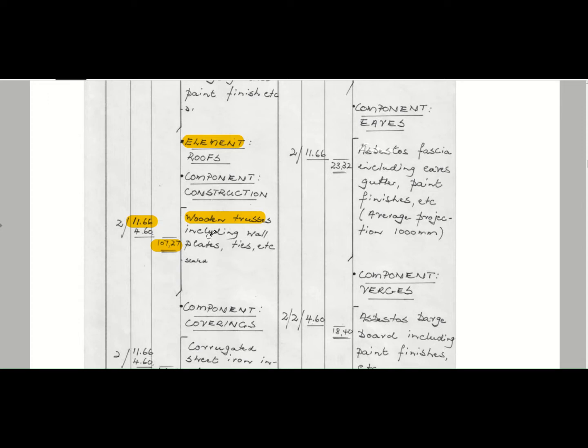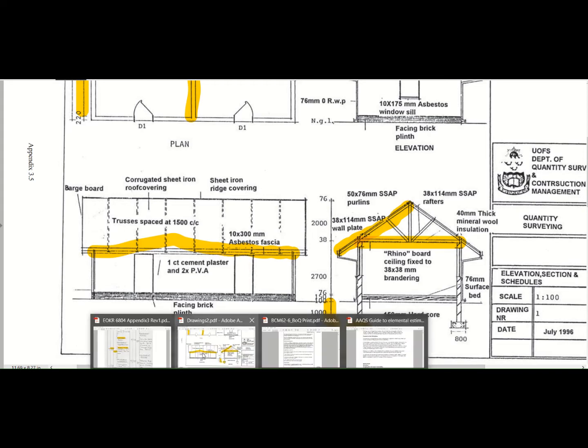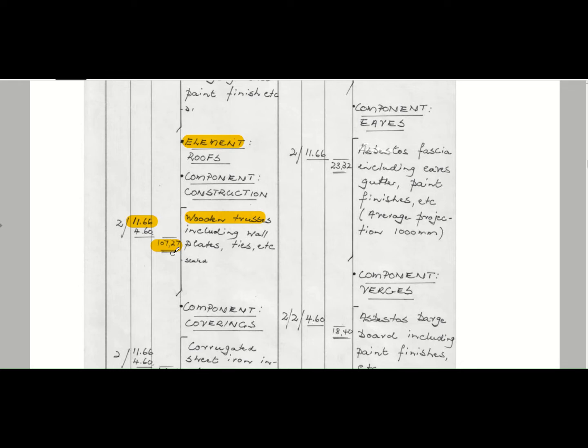The main thing that you need to remember here is to compare apples with apples. If you've got a previous drawing that you measured differently in your bills, your roof area is usually measured over the angled roof area, whereas many times you might have a roof that's measured over the flat area. So obviously the one on the slanted angle is more accurate because you can easily compare it with previous projects where the angle of your roof differs. Okay, so just note that in the example it's measured on the slanted area.